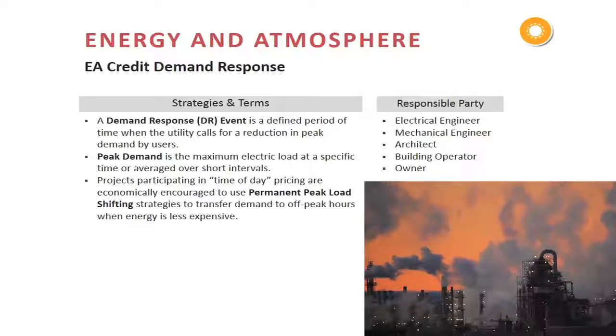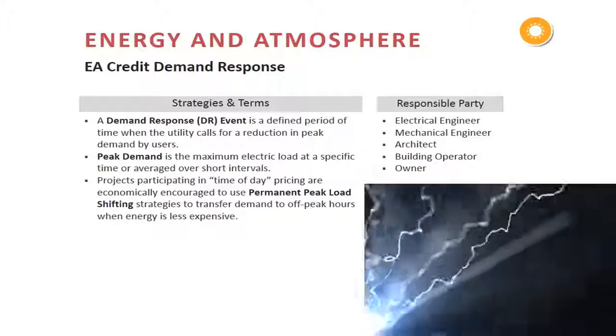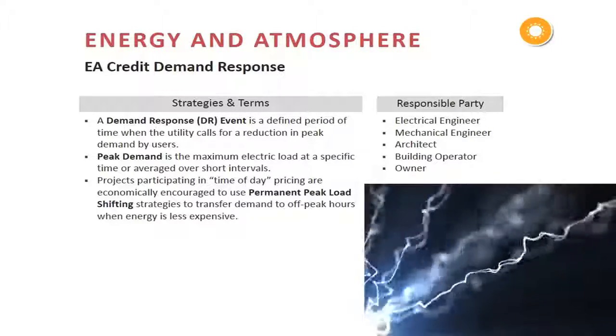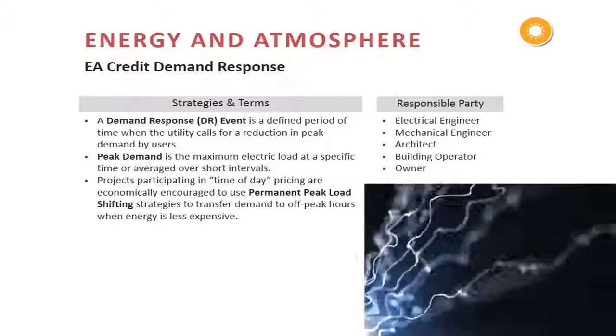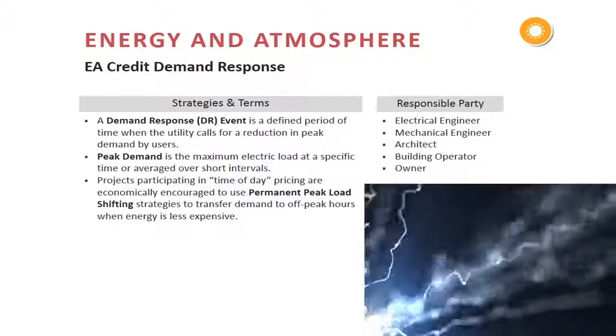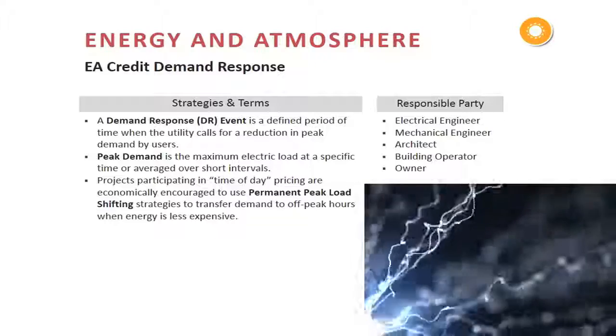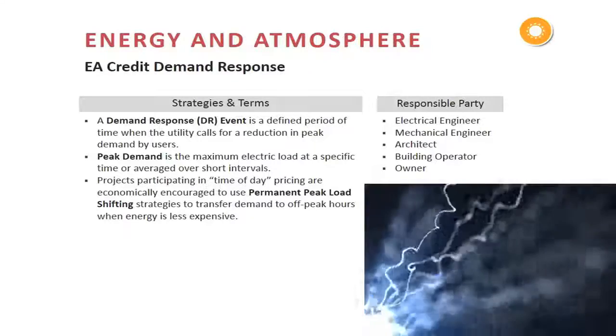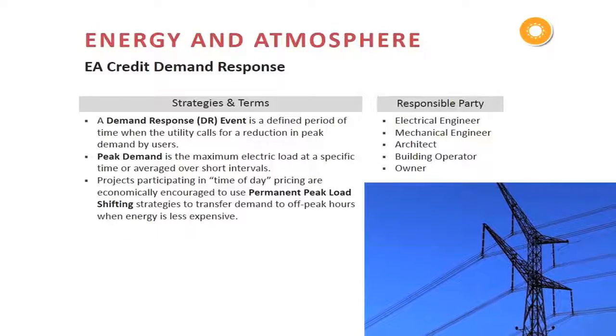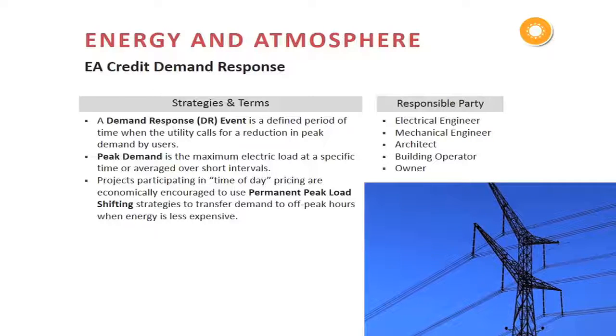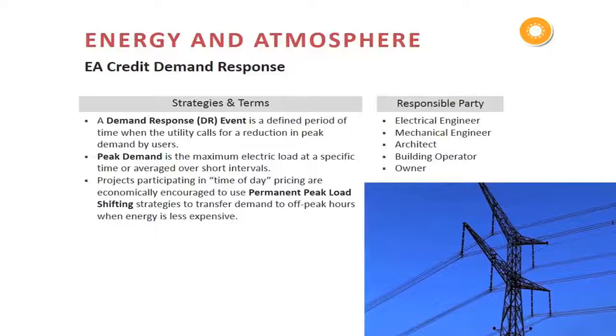Now peak demand is defined as the maximum electrical load at a specific time, or the maximum averaged over very short intervals, so over a minute period or something like that. Now, projects may have the opportunity to participate in what's called time of day pricing, where they have lower rates for their energy during those off-peak periods.